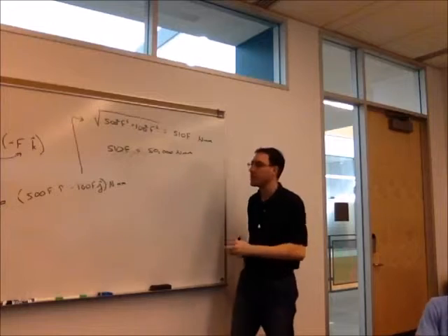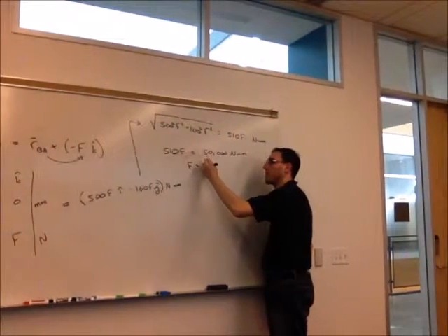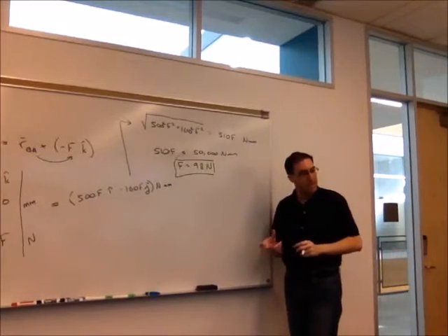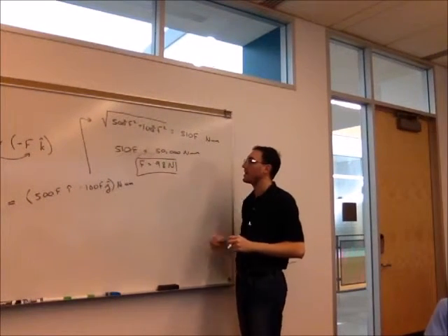So now in this equation, the last thing I need to find is F. Solving for F, the force required to have the magnitude of the couple be 50 Newton meters is 98 newtons.